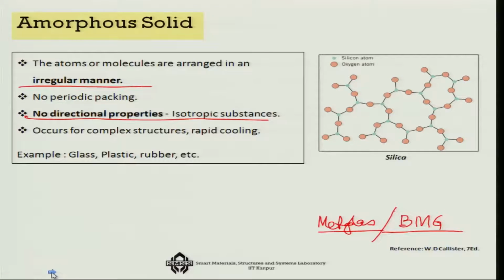Of course, the other thing, which we will talk about at a later stage, is polymeric chains. Polymers are by nature amorphous, because depending on what is coming in the cross chains of a polymer, it may never actually show a long range order. So, there are some materials which are by nature amorphous, and there are some materials which are by nature crystalline, but you can force them to take an amorphous structure, for example, bulk metallic glass or the metallic glasses.